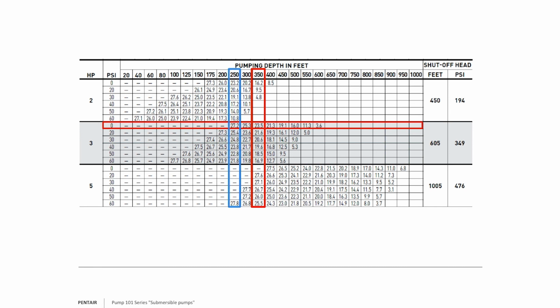Okay. If we looked at the 250 feet depth to water and then our 40 PSI, we get 23.8 gallons per minute. Okay, very close to either calculation. The reason you see a difference there is because we're not calculating the numbers precisely: in that 250 we're rounding, and 350 we rounded down from 354. Okay, so we're not calculating for all of our numbers by doing this.